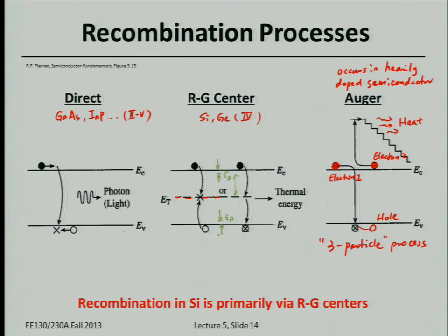Right, exactly, that's a great question. The question is, isn't that bad for a dopant? Yes, you're absolutely right. We never want a dopant with an energy level near mid-gap. That's not a good dopant, but that's a good trap. So most of the time, traps are not desirable. They're impurities that can cause recombination or generation, making it easier to generate electron-hole pairs, right?